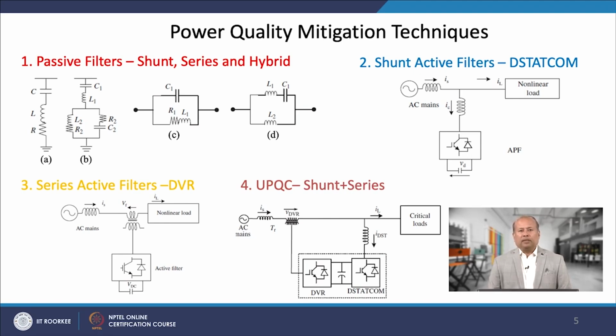These filters consist of reactive elements such as inductors and capacitors with and without switching. In high voltage AC and DC transmission systems, passive filters are much in use due to their low cost, simplicity, robust structure and reactive power compensation in most applications at the fundamental frequency.